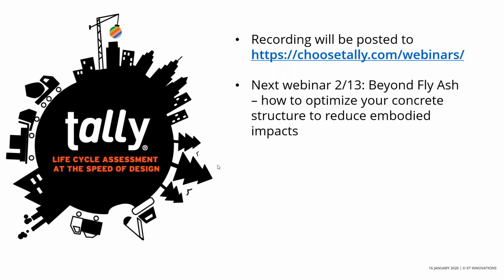But with regard to elements that may be duplicates, this is something that routinely we have to track in our office as we work with a lot of structural engineers who also use Tally for their models. Generally the way we handle that is if our linked structural model contains Tally information and we pull that into our linked model, then we would typically put our duplicate structural elements on a work set that we could exclude from the scope of a whole building assessment so that we're not essentially double counting all of that steel and concrete. Sometimes it happens that our structural models will leave off a finished flooring material or a concrete topping slab. And in those cases, we would simply assign that one material in our architectural model and leave the rest of the assignments to the structural model.